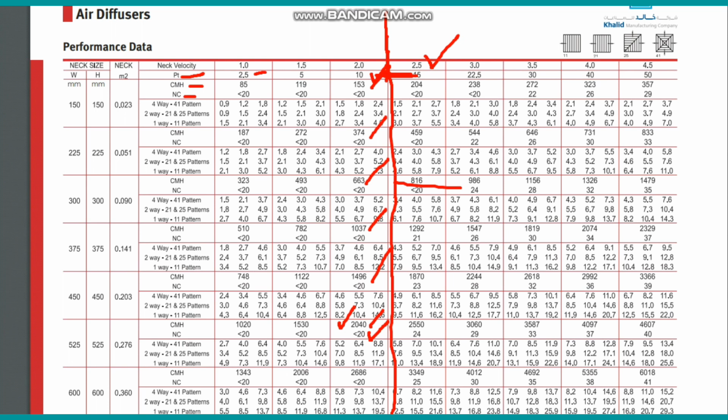So surely that 5 to 10 or 5 to 8 NC value will be increased from what you see in the technical data sheet. So normally we have to give that allowance. For example, in our case 25 to 35 NC is the acceptable value, meaning we should not go to the extreme edge of 35. So we have to keep it at 30 or 25. 25 is the really recommended one. In our case here it is 20 only, so it's really acceptable.